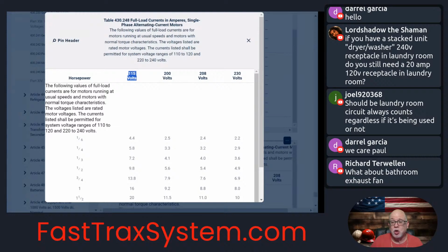Now don't get confused if it's for something like that dishwasher. That dishwasher, if it had said 10 amps times 115, then you use the 115. You use whatever they give you. In our case, it was 120. But if you get a motor question and they give you 120 or they give you 115, you use what they give you. It's just that in our case, since the motor was a 120, we know that most motors on the nameplate might say 120, but are rated at 115. So that's why we're using the 115 column, in case anybody ever got confused on that.